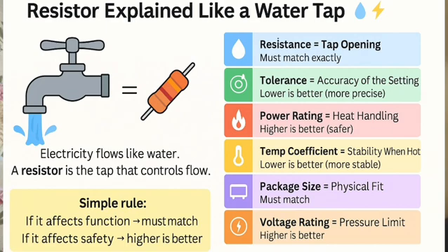The reason is that you should have the capability to handle heating. The power rating is measured in watts or milliwatts. Assume there is a half watt part number, or the resistor has gone obsolete, and we are recommending a replacement: we should select a 1 watt resistor. The reason is that it will withstand a high flow of current and heating within the circuitry.